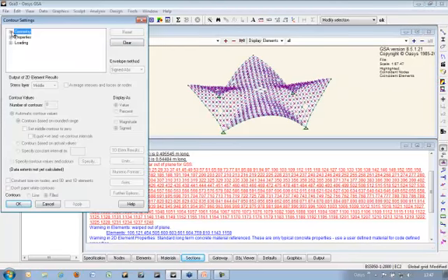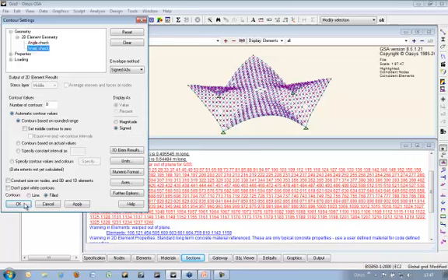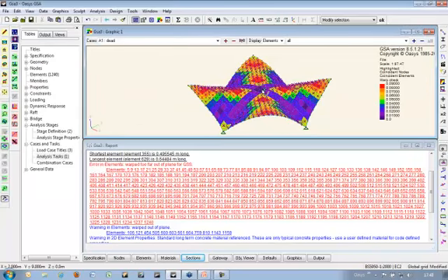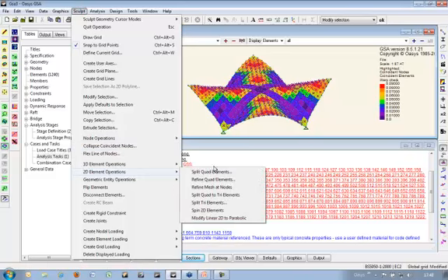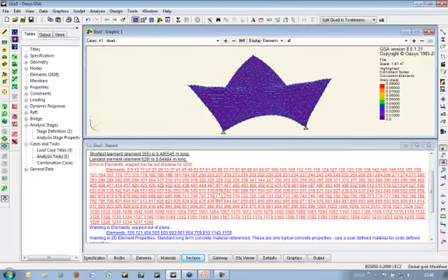In fact, if I look at the geometry contours, we see that just everything is warped apart from the 4 in the middle. So let's use the sculpt tools to split quads down to tris. And tris, obviously, triangle elements do exist on a plane, so you don't have the warping problems.